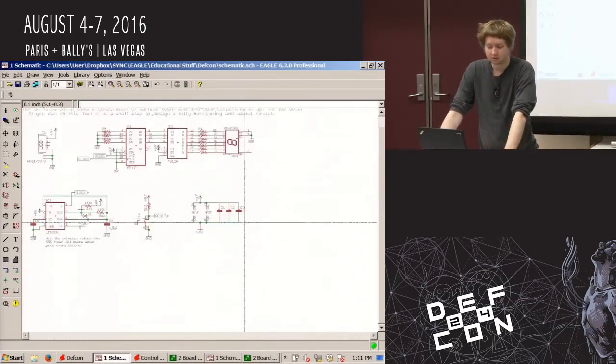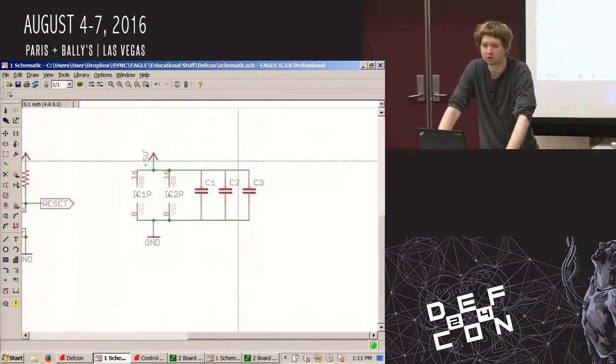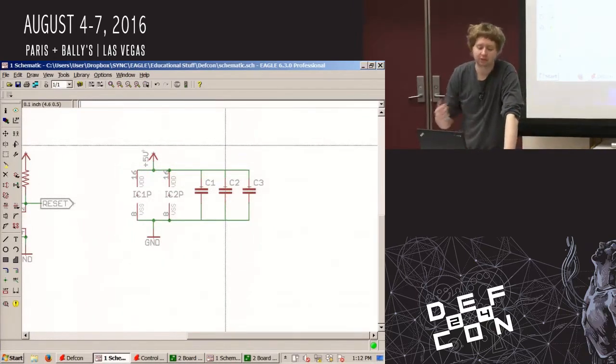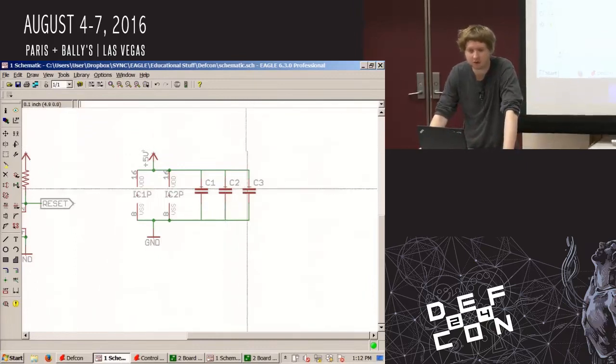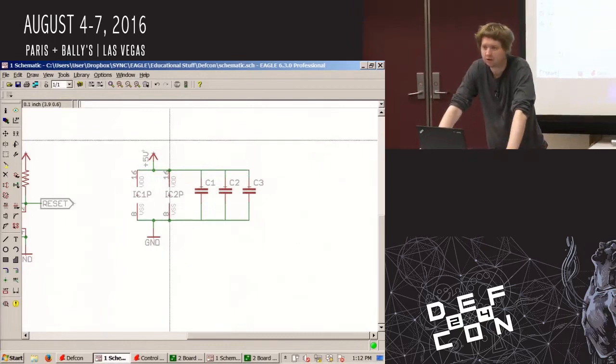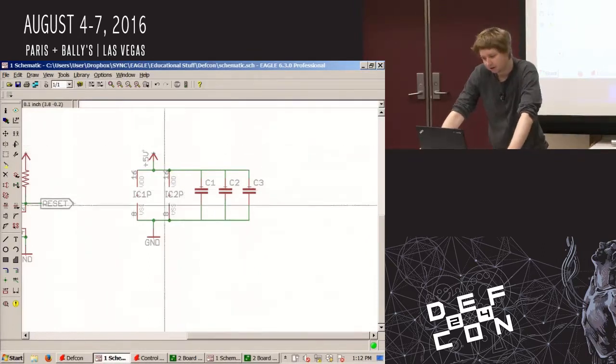So a lot of times you'll see them just kind of off on their own on the schematic. So what the bypass capacitors do is it effectively shorts out the antennas you're creating. So every time you have a trace, it has a little bit of inductance. And if you're running a high frequency through it, you now have an antenna. Depending on what you're doing, you could either get people with ham radios mad at you, to the FCC being mad at you, to a compliance engineer being mad at you if you have to go through that. It might also just make your TV do weird things if this is just kind of being breadboarded out.